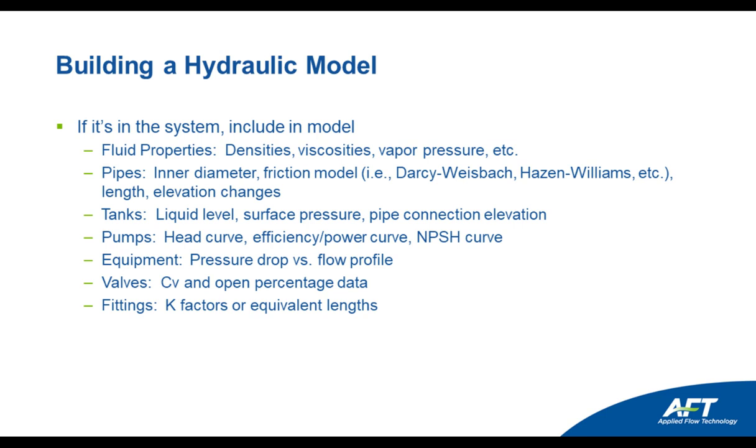Not necessarily. This is where you still have to apply good engineering practices and good engineering judgment when you're doing flow analysis. When you think of the Darcy-Weisbach equation for frictional loss in a pipe, the frictional loss is much, much more dependent upon the pipe diameter than it is on the length.